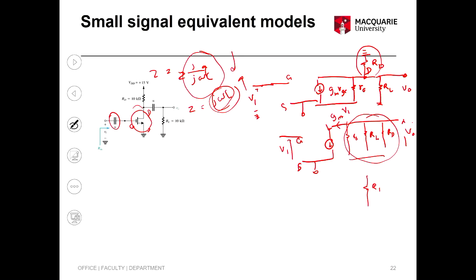So what are we trying to find here? We are trying to find the gain. Gain means voltage gain, Av, Vout versus Vin. So I just want to find this for this circuit, okay? So I'm trying to solve this circuit so I can find Av. Now, it looks like I get a current gm V1 here, and that current, because it's open, will go through this loop, right?